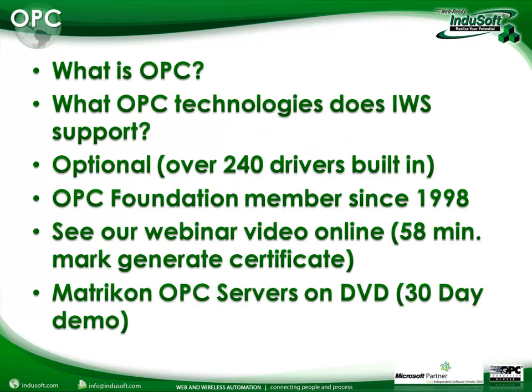First, we're going to cover what is OPC and what OPC technologies or communications InduSoft Web Studio supports. Just to let you know, OPC is something that is optional within InduSoft Web Studio. We have over 240 drivers built into different communications protocols, and it's generally recommended that you use those, as they're built in. You don't have to go through an external piece of software, and they're included as part of the product, whereas most OPC servers are going to be an additional charge for each and every deployment.